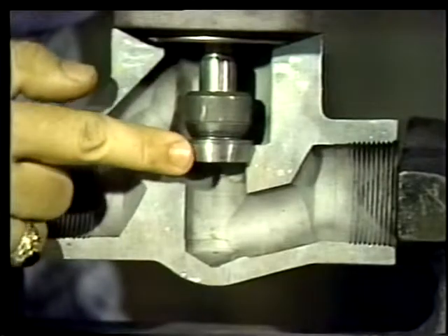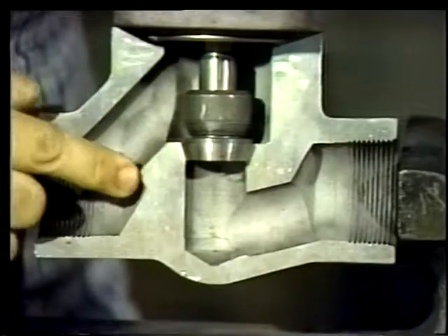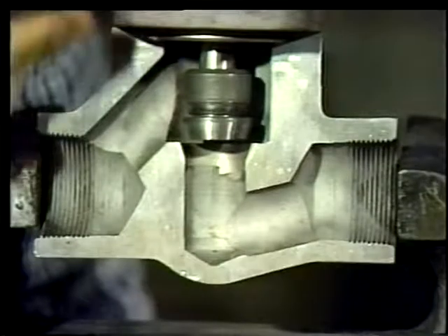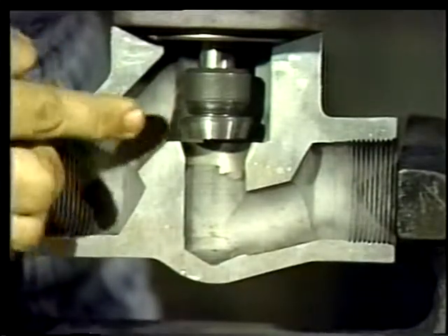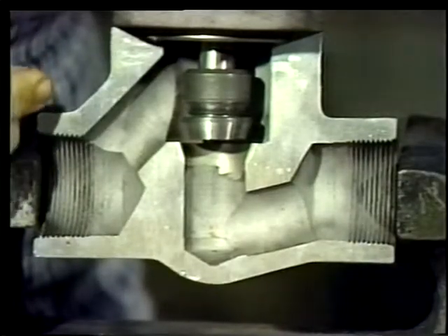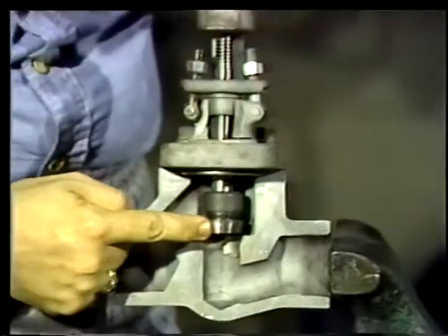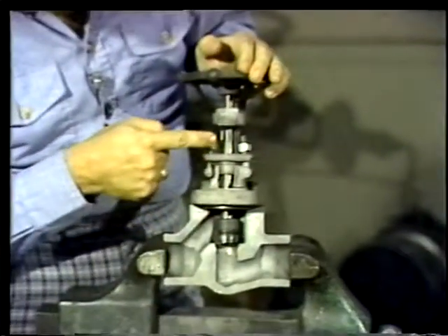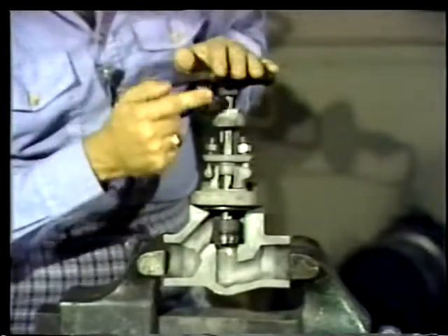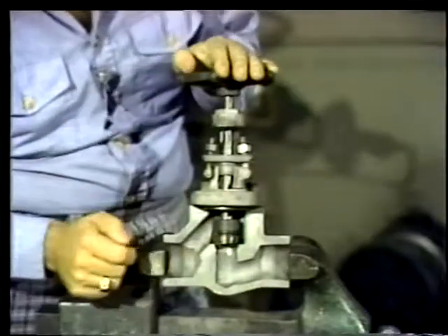The disc is the part of the valve that presses against the seat to stop flow. Now, when a disc is partially open, that is, not completely closed against the seat nor fully raised, it is in a throttled position. This partially open or throttled position is used to regulate flow. Many discs like this one are attached to the stem that connects to the valve hand wheel or operator. The stem transmits the rotation of the hand wheel to the disc inside the valve.